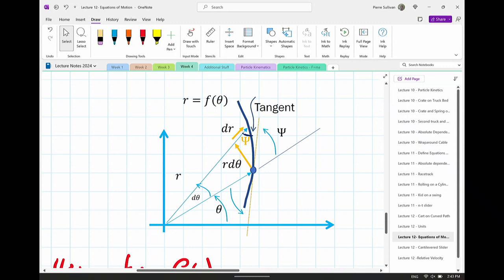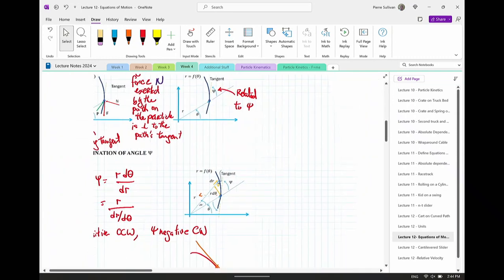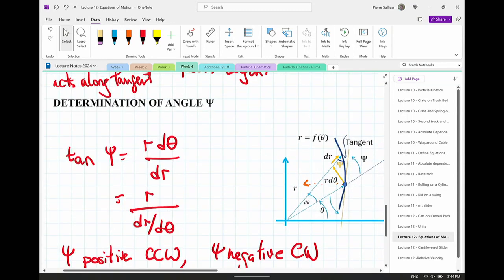We always want to know what the normal direction is and what the tangential direction is of a particle in an r-theta system. We don't have to know that in an NT system because we always describe it with respect to the curved path. It's going to be different because on an NT system there's no origin, but the center of curvature is just going to be straight through there. So for an NT, you point in towards the center of curvature. For an r-theta system, you have to reorient everything, and when you reorient everything, you end up with this relationship right here.